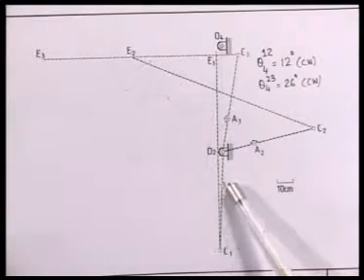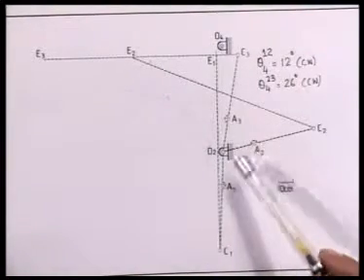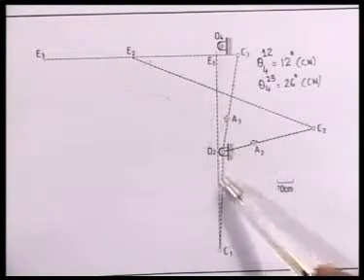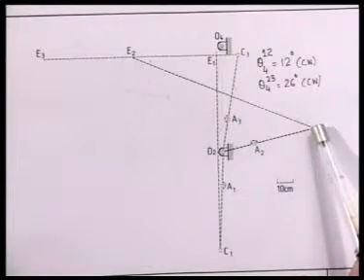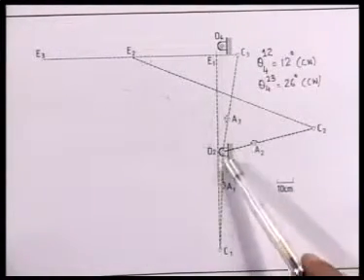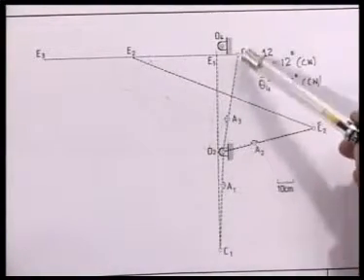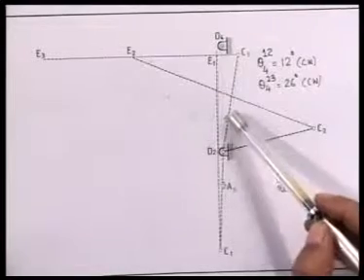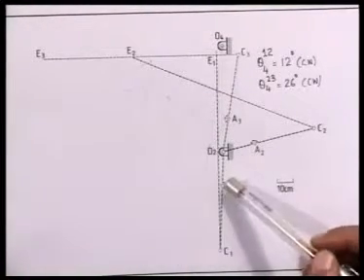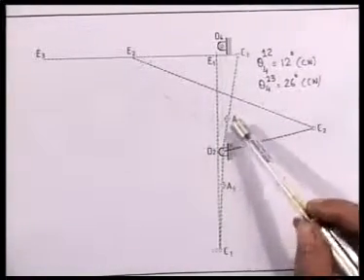So we can immediately determine where A2 and A3 are, because the distance O2A does not change. In the first configuration it is here. Because C2 is given, O2C2 is the link and this distance remains same, so I can determine A2. And O2C3 remains same, so A2 comes to A3. So I know the 3 positions of this revolute pair at A, namely A1, A2, A3.